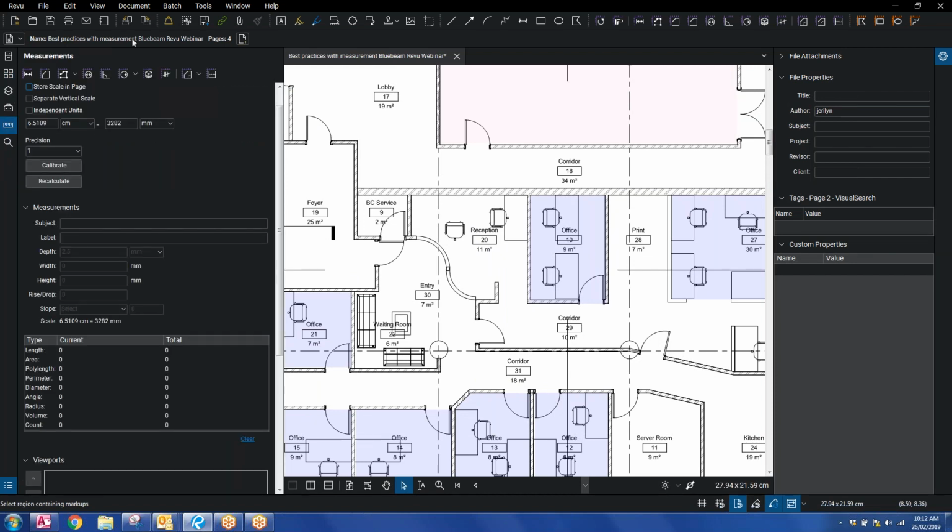If you have a strange or curved area, dynamic fill fills up the room for you; all you have to do is create a boundary yourself. This tool is available in 2017 and above, and it has been a gem to so many people who have been using Bluebeam for years and having to click so many times to do an area. Now with dynamic fill, it solves everything.